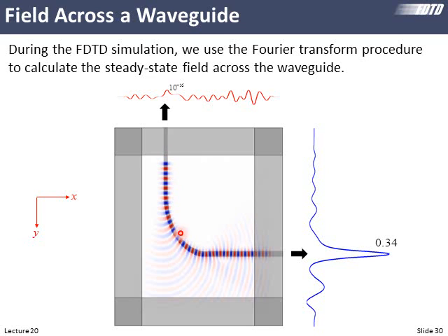If it were a tighter waveguide bend, we might see some reflections. But we do see a good amount of transmission through this. Not pure transmission. There's certainly some waves being leaked out, and we see that in terms of oscillations outside of the guide. And we excited it with a unit amplitude source, and we're getting out an amplitude now of about 0.34. So it's lower because power has leaked out. There's just less left in the waveguide.